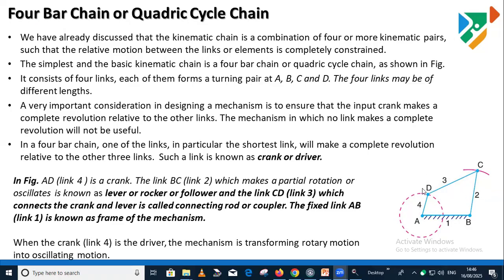Whenever we are cleaning the glass of any vehicle, we just mount that wiper on link number 3. As you rotate the crank, that wiper oscillates about this fixed position, so that we can clean that particular glass. Depending upon the area of that glass, we can change the dimensions of the wiper. This is the special mechanism where we achieve rotary motion as input and finally rotary motion as output. But in between, we are targeting the trajectory of that coupler, or you can say oscillator link, and we can clean that particular pattern.